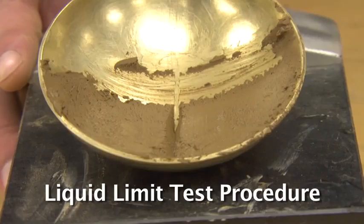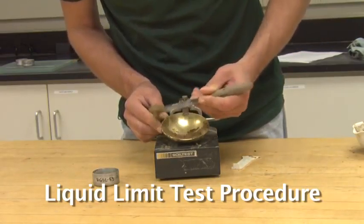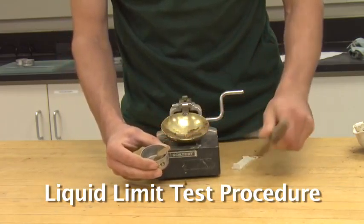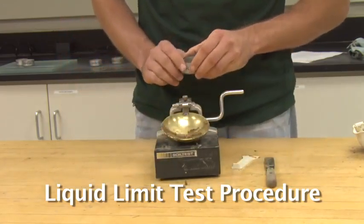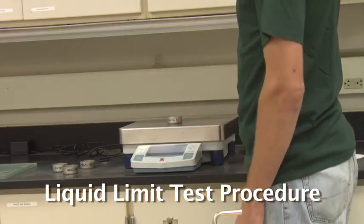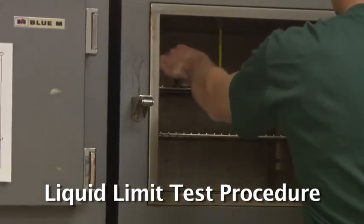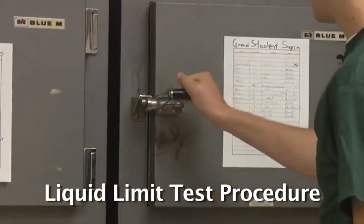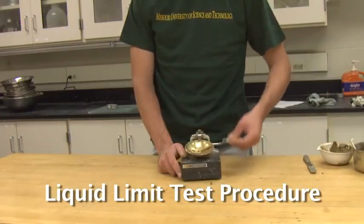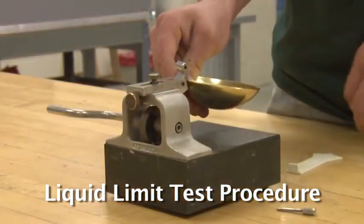If the number of blows falls between 15 and 20, scoop out some of the soil and place it in one of the pre-weighed tare cans and record the new weight for moisture content determination. Place the can with the soil in the oven and reweigh it again in 24 hours. If the number of blows falls below 15, mix the soil to dry it out, clean and dry the cup, and repeat the test.